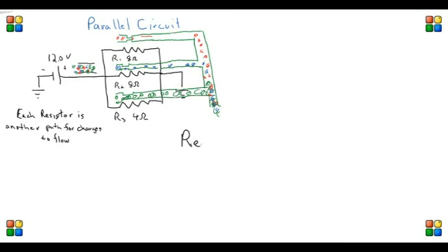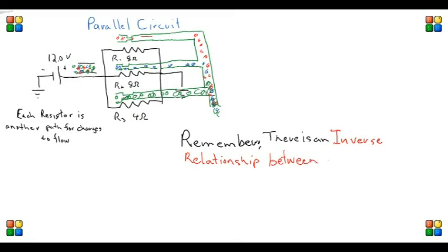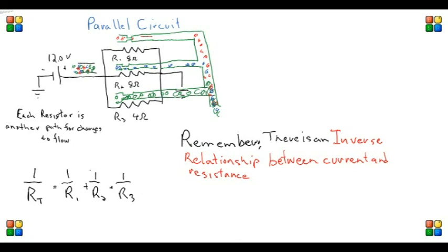Well, a flip is just the same as an inverse in a way. But remember, when you're thinking of parallel circuits, the relationship is inverse to that of a series. So more resistance in series, less current flow; more resistances in parallel, more current flow. And that's important to remember. So the math becomes an inverse math problem. But the bottom part, all the R's are the same. To inverse it, you put 1 over it.